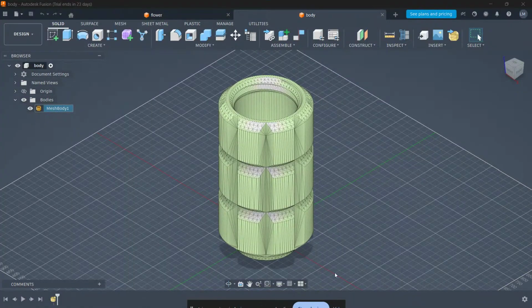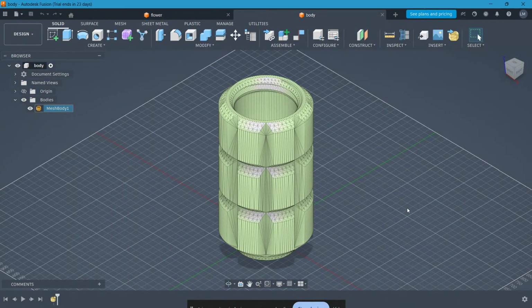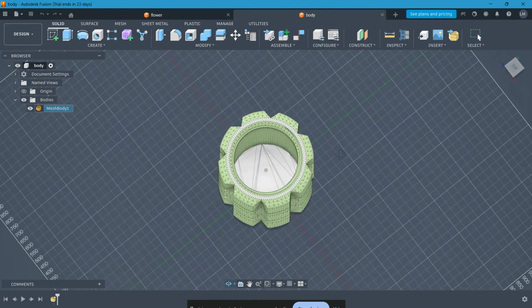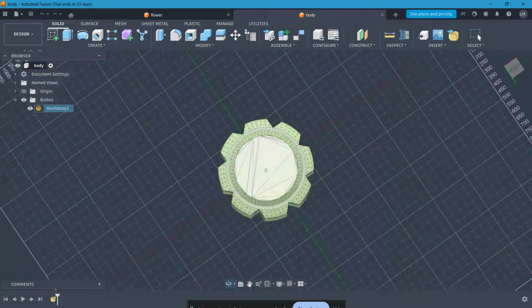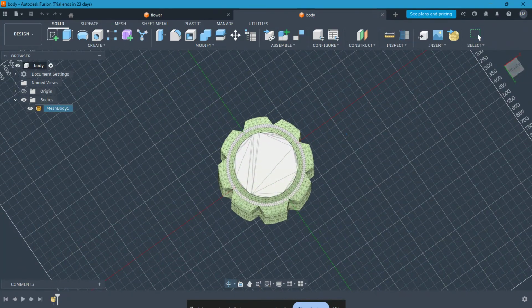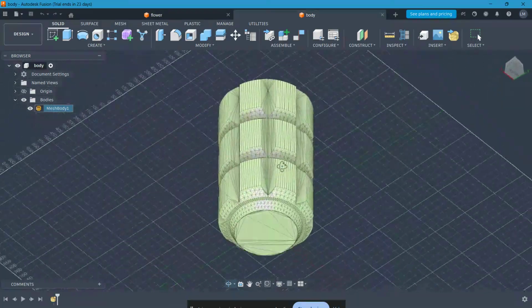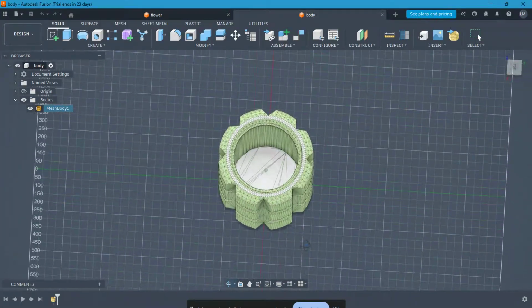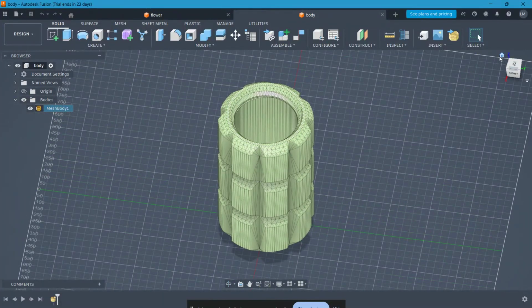In today's video, I'm going to show you exactly how to fix the Fusion 360 meshing error called self-intersection. If you've tried to generate a mesh and Fusion 360 suddenly throws a self-intersection error, it usually means some part of your geometry is passing through itself or overlapping somewhere in the model. The good news is, this is a very common problem and it's usually quick to fix once you know what to look for. I'll walk you through the most common causes and several simple ways to repair your model so the mesh generates correctly.